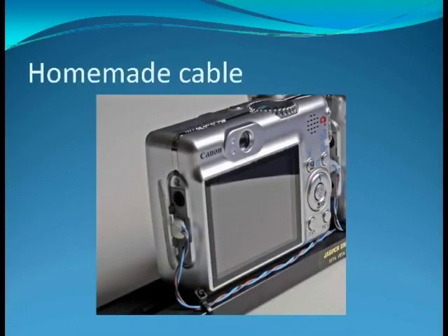And I know what you're saying, no, I probably can't solder that. Well, actually, you probably can. What you end up with is something that looks like this. Now, that strange little blob is after you've soldered these wires to that connector. There's nothing to hold them on except the solder, and it is going to break. So what you're going to do is take hot glue, like from a hot glue gun, and put a little drop of it on it. Or you can take an epoxy putty, like this. It's sold in modeling supply houses for working on model airplanes. And it forms a really good insulator and will hold those wires on as good as something that was built in the factory.